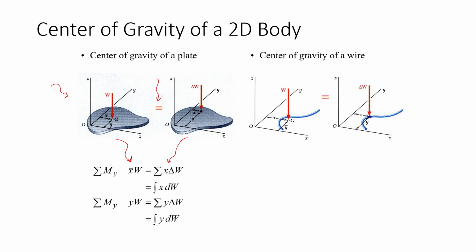If I'm going to say it in layman's terms, you're adding up pieces of the whole body with their respective center of mass. For example, I'm going to add up the weight of my hand and the corresponding centroid of my hand, plus the weight of my head and the corresponding centroid of my head, plus my body, and so on and so forth. When I add them up, it is just equal to my centroid times the total weight. So that's the idea.